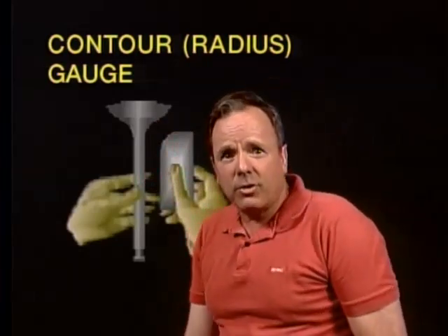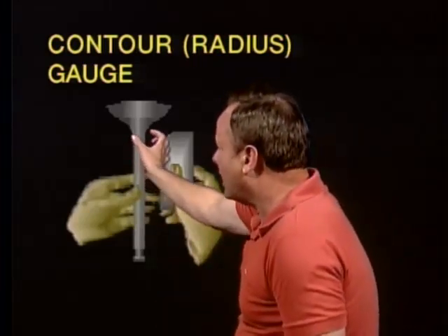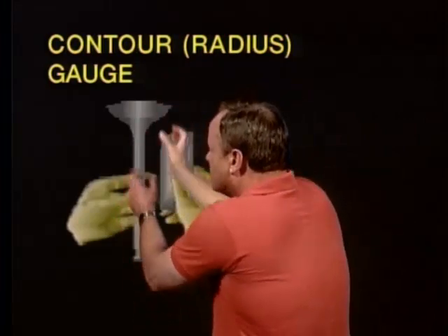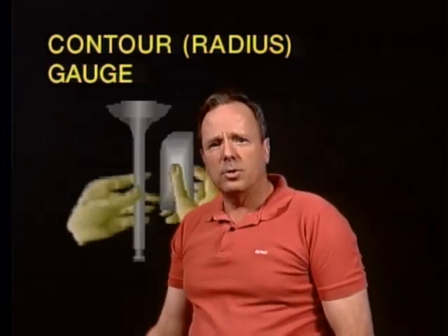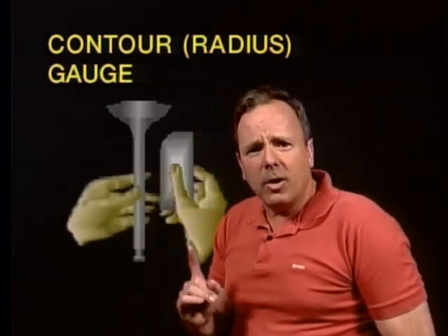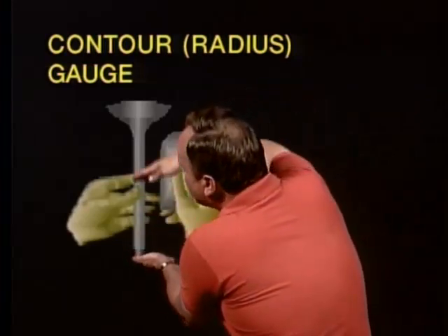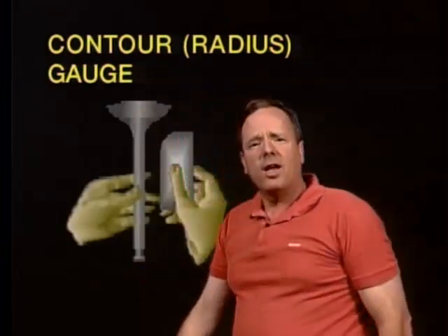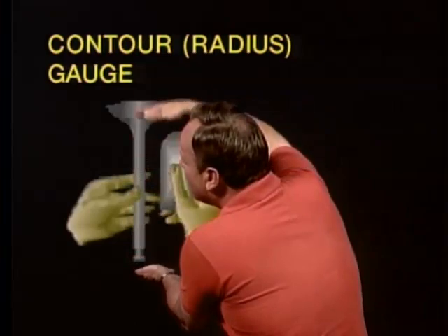Now, another method you could use to check for stretch is you could measure a reduced stem diameter. If it stretched out, the stem got thinner, and therefore it would tell you that the valve had stretched, and you do that near the neck. Now, here is something that is surprising. Here is a way that is not acceptable to tell if a valve has stretched. And that way that is not acceptable is to measure the length of it.